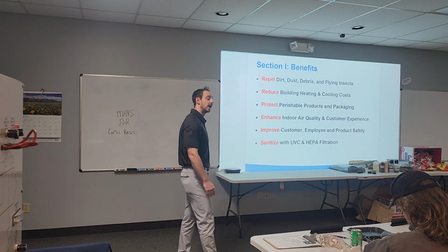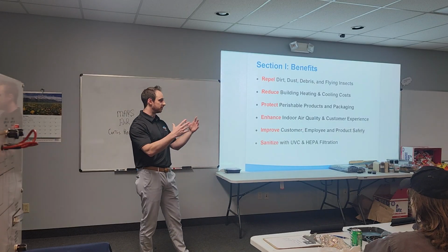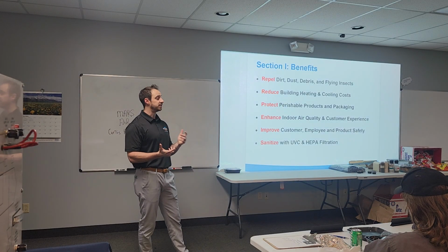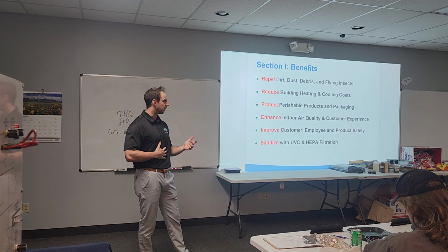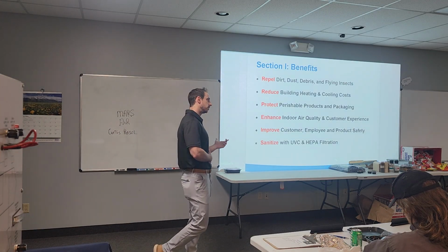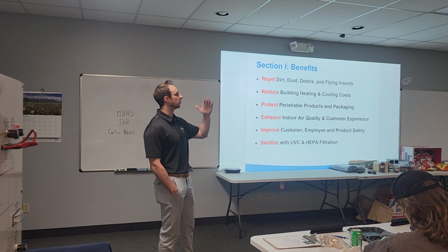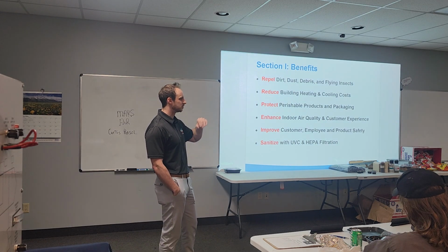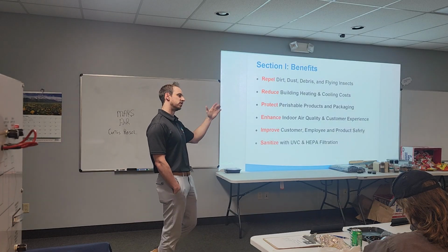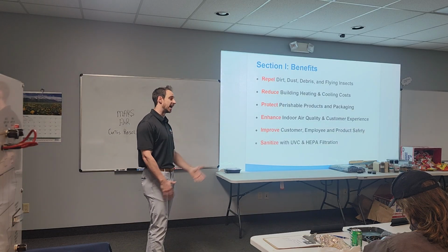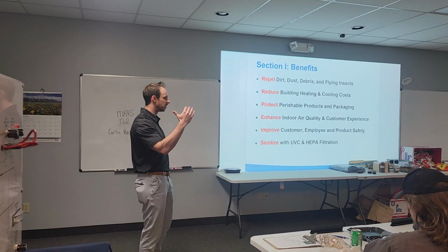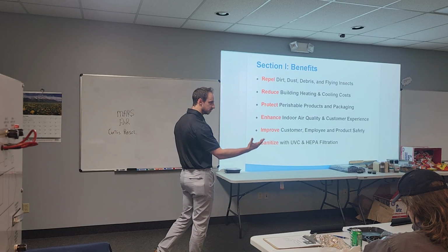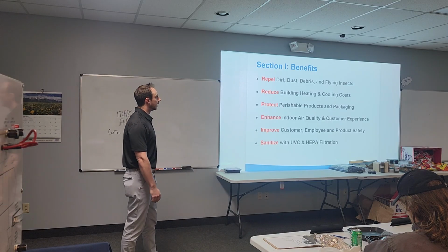And to add to that, I know ECM motors are supposed to be more energy efficient, but we actually see very comparable energy efficiency with the PSC motors. The reason is that air curtains turn on and off so much. The ECM motors have a bit of a ramp up time, so you're not getting as much effectiveness. If the door opens and there's a ramp up time, especially in high traffic, it's just not syncing as well, and it's not as efficient. But it's a good question. A lot of people are definitely moving that way.